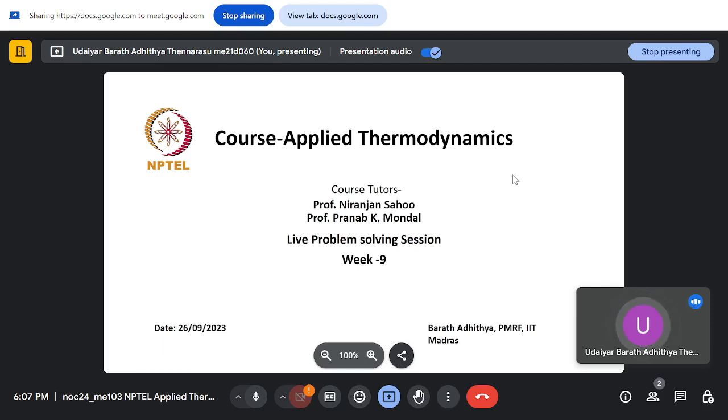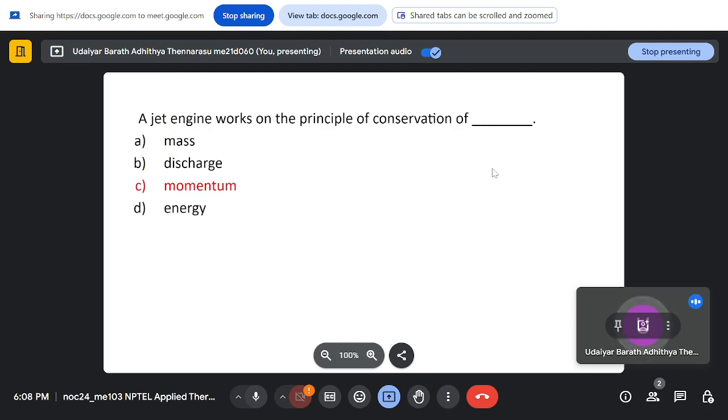In a turbojet engine, you have a diffuser at the start, and the air coming in then goes to the compressor after the diffuser. So the velocity is brought down, and then you compress it, and the process remains the same. This is a turbojet. The initial bringing down of velocity and the pressure increase is called the ram effect. That is what is used in a ramjet engine. This is to give you a brief idea on aircraft engines. We'll see numericals and MCQs on this.